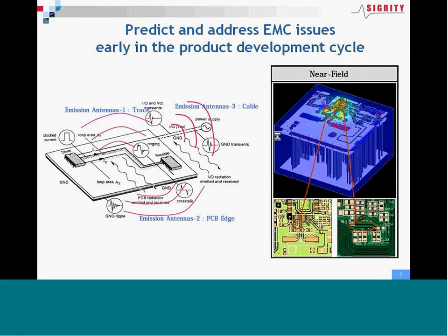So these could be signaling traces, as in a serial or parallel bus. They could be clock traces, and clock traces are especially susceptible to radiation for synchronous clocks. But anything that looks like a microstrip trace that is exposed either on the top or the bottom of the board can leak energy and is considered by our analysis. Also, power plane cavities or power ground pair cavities can radiate. They can radiate because they have power ground noise. They can be decoupled, but you still have edges that are not tied together all around the perimeter, and those edges can leak through an equivalent magnetic current.